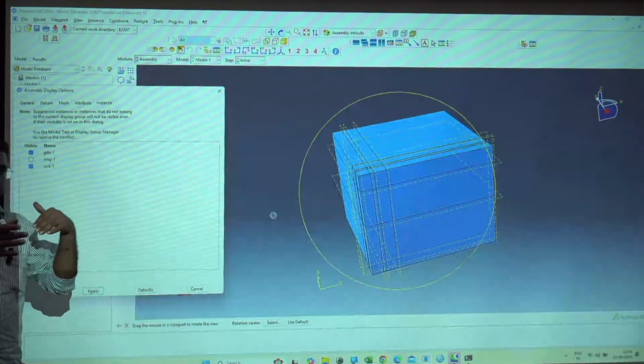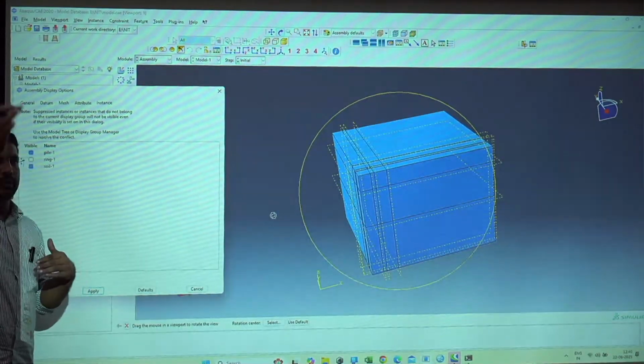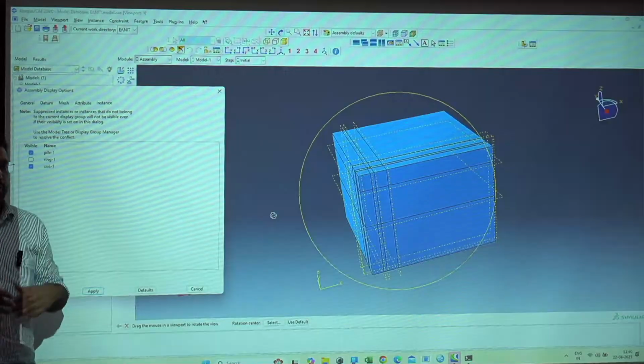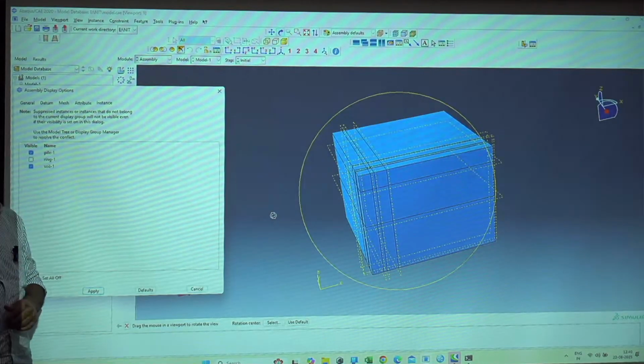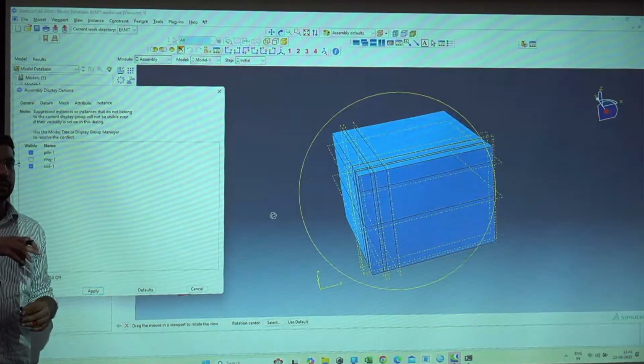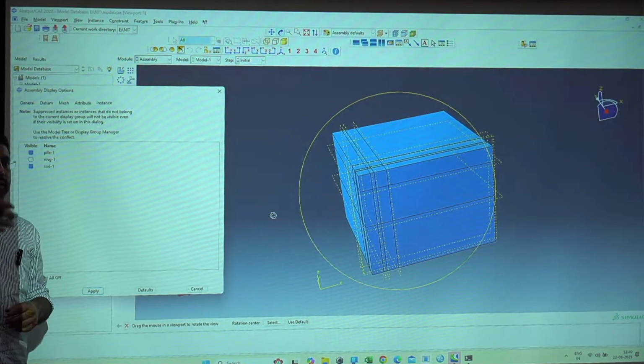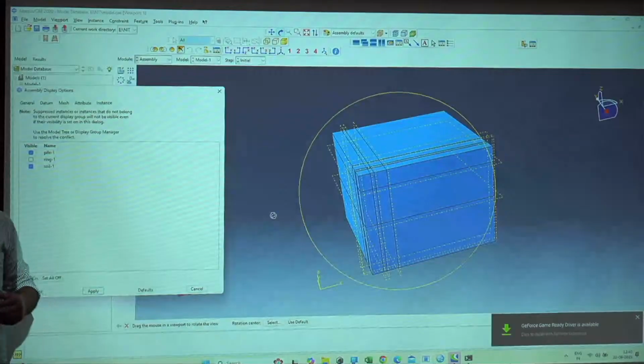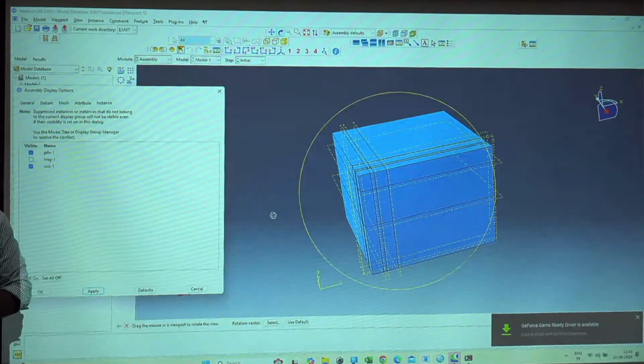To get the finer mesh near the structure and the coarser away from the structure. Okay. If you have the finer mesh all over the soil domain and as well on the structure, then your computational time may take 2 days, 3 days, or maybe 1 day. Okay. Yes, yes. I will show you how we are doing.